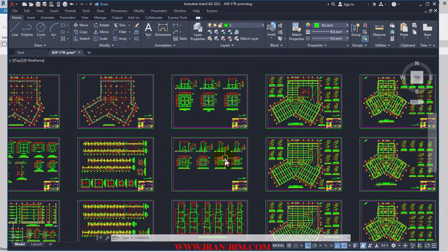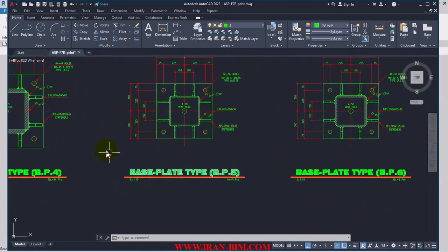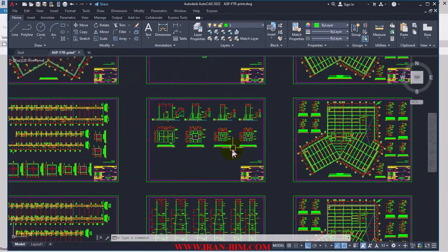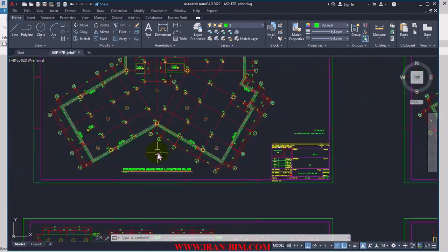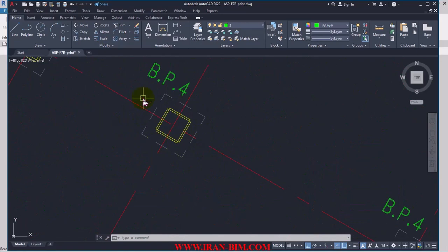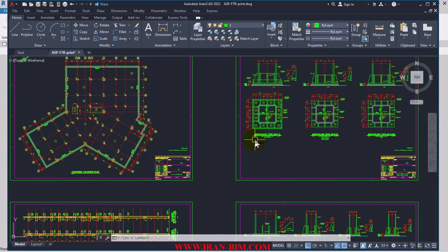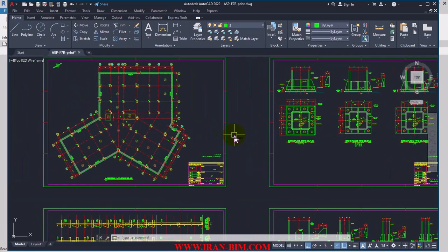For example, in CAD we have scale, which means you have the details in the scale of 1/10, and what you see in this scale you'll never see in the scale of 1/100. It means that its details are general, and to make these details clearer, they've put them into scales. Since you are modeling everything one-on-one in BIM, scale means nothing from a geometry viewpoint. Here, details means everything.